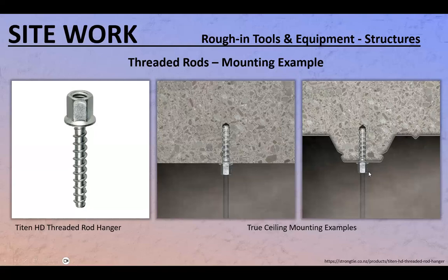Well, it takes a lot longer than this, and you are going to destroy a lot of drill bits, because first you have to make a hole in the steel, and then you need to use another drill bit to keep drilling into the concrete. You're going to lose a lot, because once you get through that, if you drill into the concrete with the steel drill bit, you're going to dull it up. Right? But sometimes it is what it is.